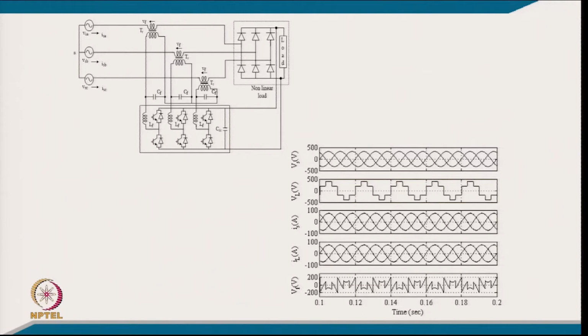So, in the circuit here also we have a common DC bus of the load and series active filter, and we inject the appropriate voltage in a manner that these currents are in phase with the supply voltage at unity power factor and they are harmonics-free balanced sinusoidal currents.